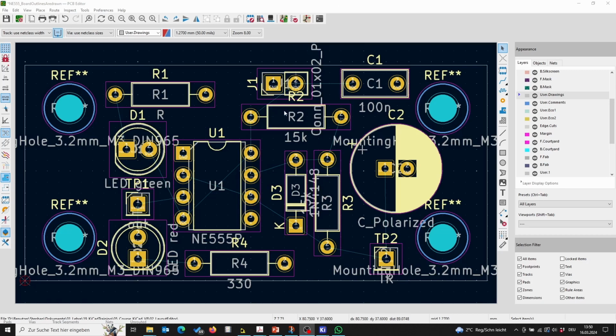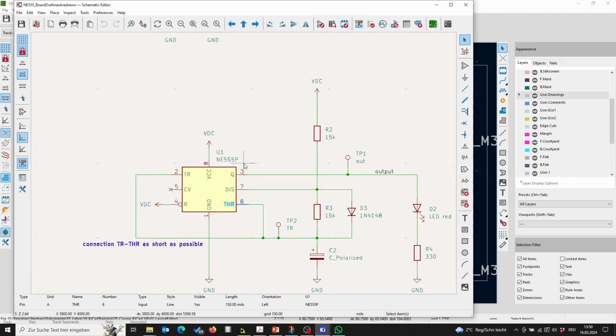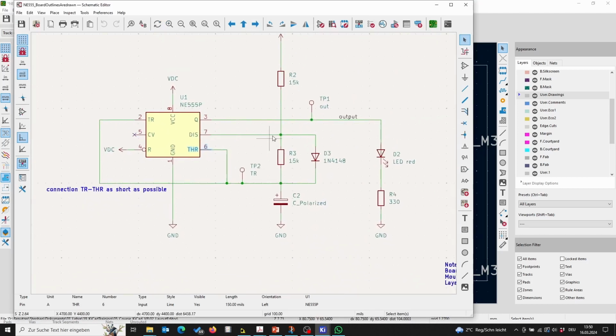So check, for example, pin 7, which, if you remember correctly, is this net going on the diode, and later the net pin number 6, the charging and discharging way, in order to see if we have any crossings. Let's do it here. We highlight the net connected to pin number 6, our charging discharging current.